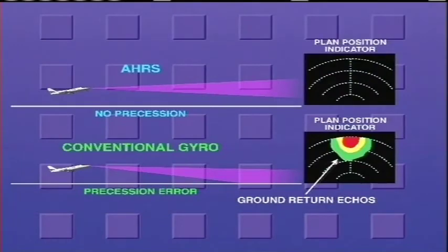Without stabilization, the antenna tilt angle is referenced to the longitudinal axis of the aircraft and will not be corrected by the gyro inputs during aircraft maneuvers. During maneuvers, heavy ground returns will normally be displayed. Antenna stabilization loses its effectiveness when the combined pitch, roll, and tilt angles exceed about 30 degrees. These limits can be exceeded during high pitch and roll maneuvers and will cause heavy ground returns to be observed on the display unit.